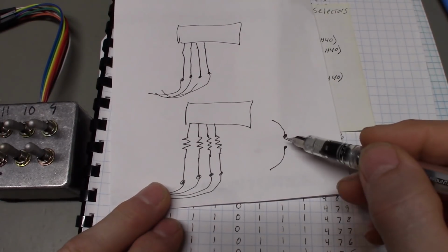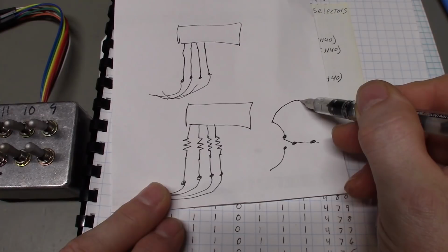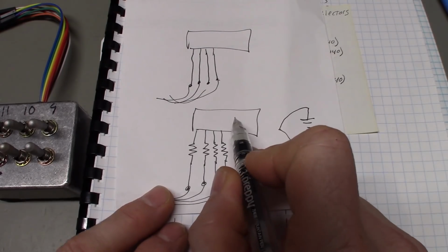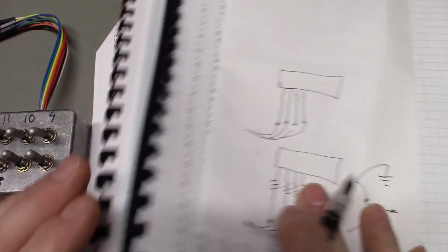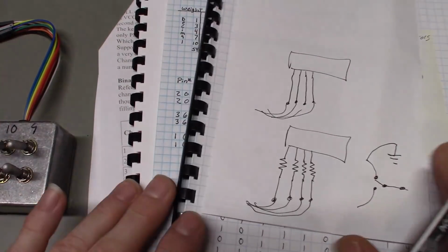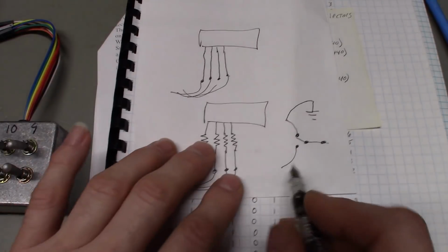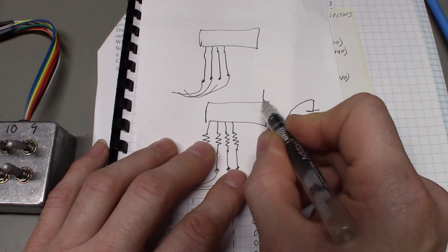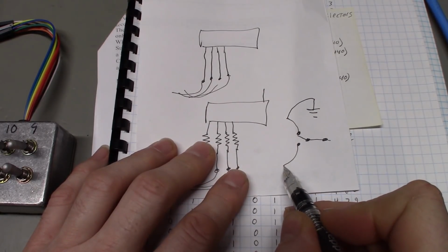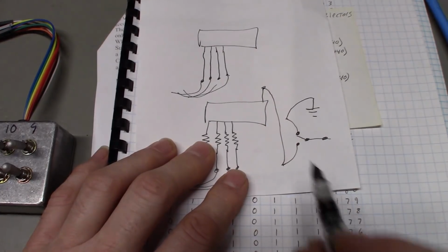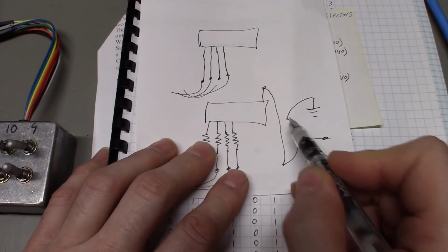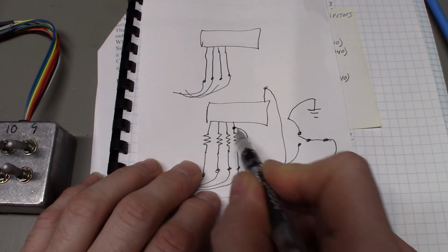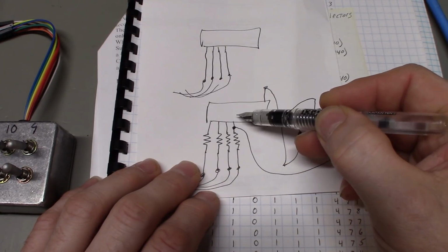But in this case, what we'd have would be one of these would go off down to circuit board ground. And that's it. And then the other one, wherever your voltage supply is, you again pull the data sheet, or you can go to the Radio Mods website and pull down the chart for whatever PLL you're working on. What you'd want to do is find the pin on the PLL chip that is the voltage supply into the PLL, and that's where this other line would go. You'd tie that to that one. So that's your voltage source or ground source, and then the toggle switch wire would come over and attach right there. Because remember, I said that gets attached to the side that's closest to the PLL.